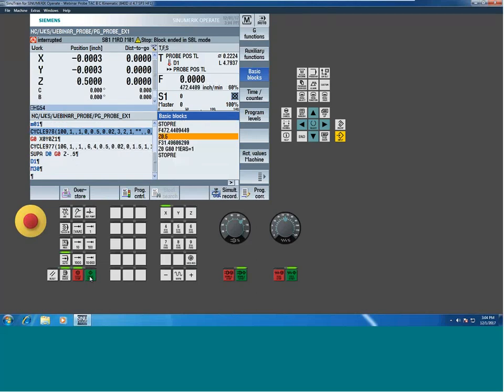We like our stop reads. There you go. There's your MEAS command. So this is the function that the cycle's calling to perform all of these tasks. When I'm making custom cycles, I try to use the cycles in conjunction with each other when I can. But if I can't, I'll go right to the MEAS cycle and let this handle it. And let's finish her up.